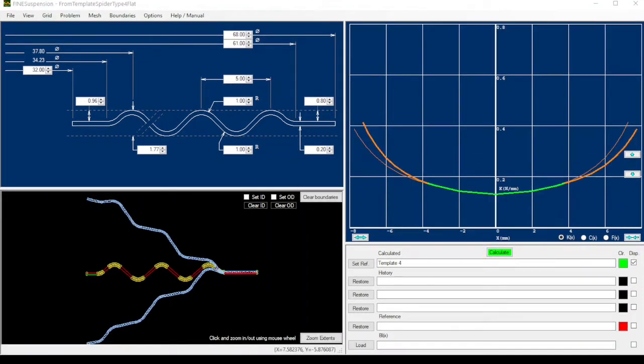After calculation, we see the stiffness curve, Kms, in the right window. This curve is U-shaped and it has a nonlinearity because there's a mirror line which does not overlap the curve. Instead, we can show the inverse curve, which is the compliance, and this has a maximum at 0, and the value is displayed. The green part is for 75% of this compliance, and that is defined by IEC 62458.